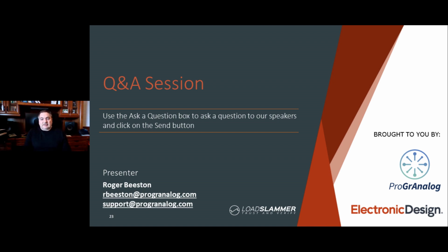You can get the models from Xilinx, and if you're using another large digital ASIC from someone else, the trick is to understand the power bandwidth of the package, not the bandwidth, but the power bandwidth. That is the trick to ascertaining the slew rate you need to be testing to. I don't know if I answered that question. Did I answer that question? I think so. Okay. All right.